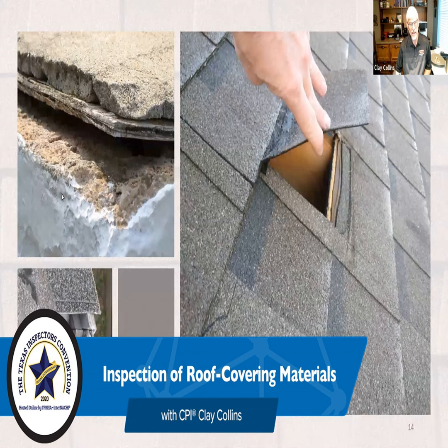So what about what you can miss here? Well, obviously that tree's in the way. I can't get up there because it's 2 stories all the way around the house. If I'm going to explain to my client that I didn't get on the roof, I might want to talk about what can't be seen, because you're going to have cases like this. You have the high side of that chimney, and there's absolutely no way you would be able to see that from the ground with binoculars, or from the roof eave on a ladder.